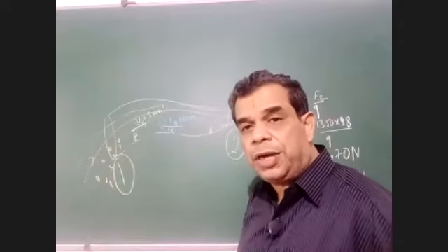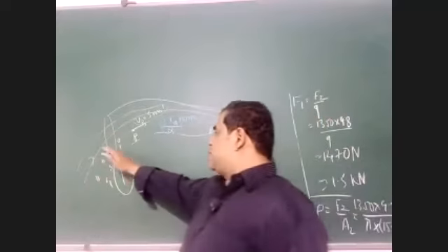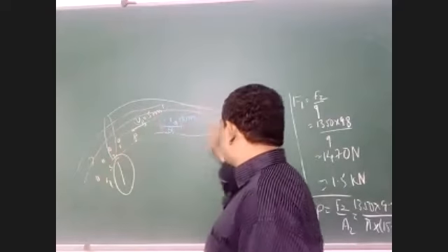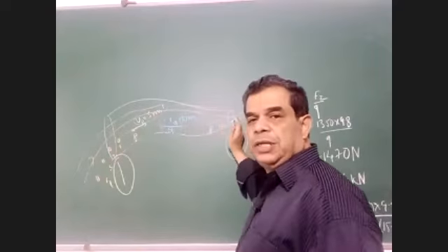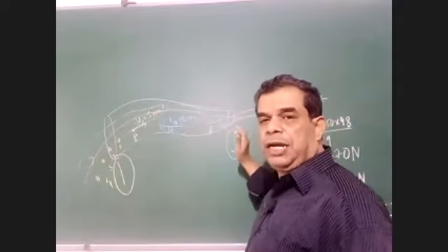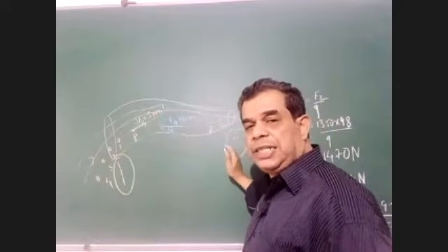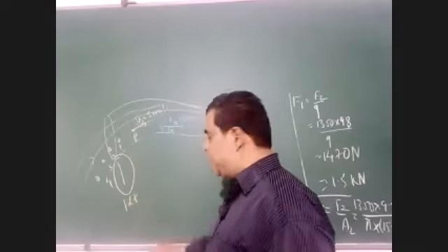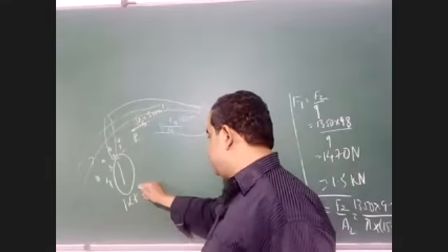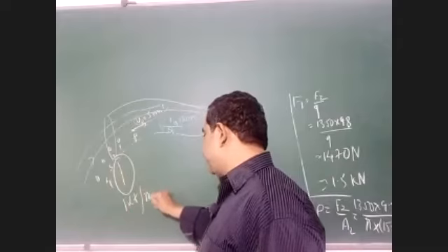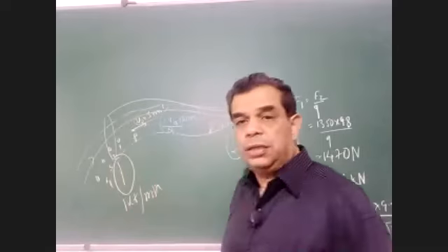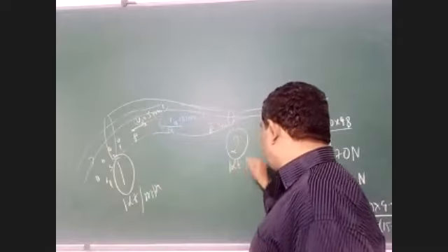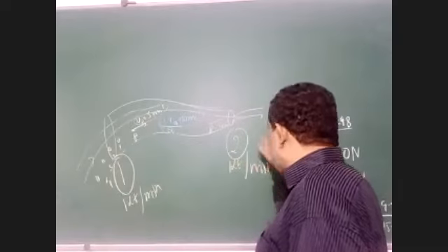How much mass enters here per unit time should be the same as the mass leaving this pipe at the same time. Say 1 liter of fluid, say water, is entering per minute. Then, because of the steady flow, 1 liter of water should come out per minute here also.